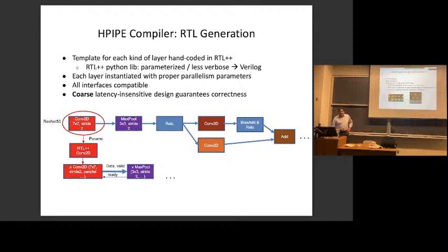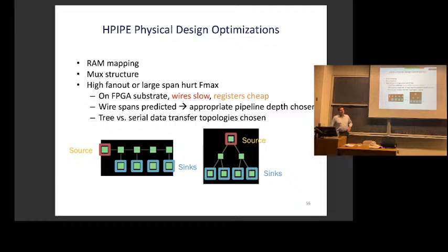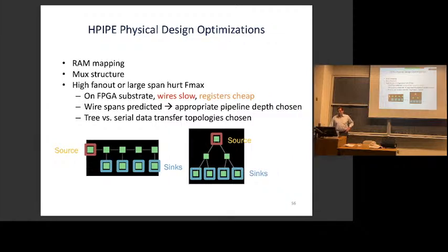The other thing that this domain-specific compiler does is it's pretty good at physical optimizations. So it not only outputs the RTL, that RTL is written to get very good performance on an FPGA. And we're going to talk about this later in the course, but basically, when you're designing FPGA circuits, you need certain blocks, you need certain RAMs.